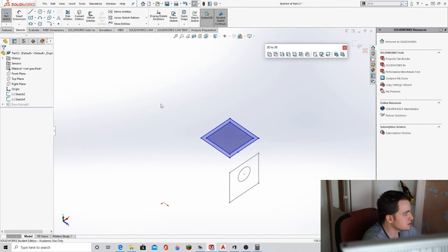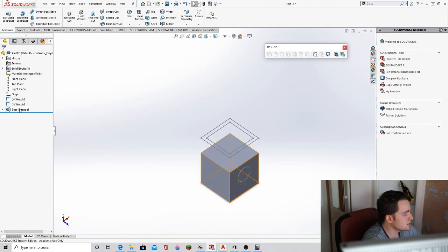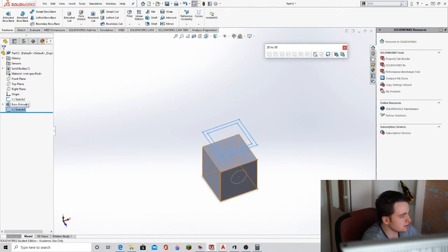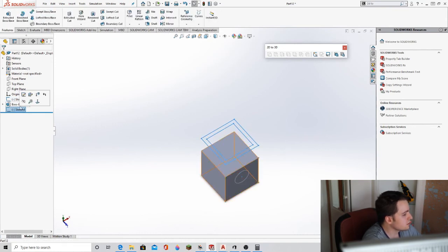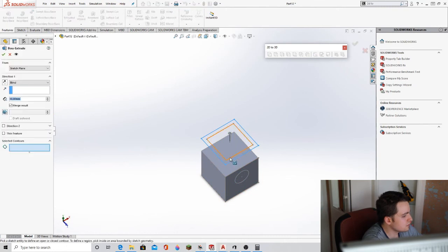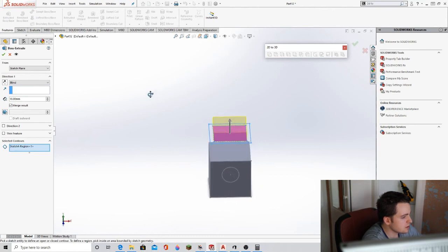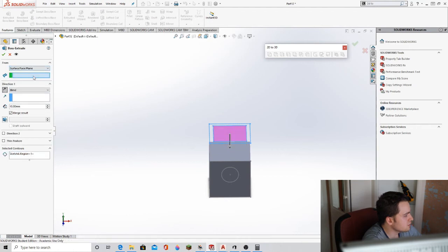So we sketch. Oh, as you can see, does this need to be lower? Yeah, sorry, I got this the wrong way around. They need to be lower than the features in order to be visible. The center one, because we want to have the thickness, we don't want to get rid of the outside. Reverse, and from surface to plane, so that.